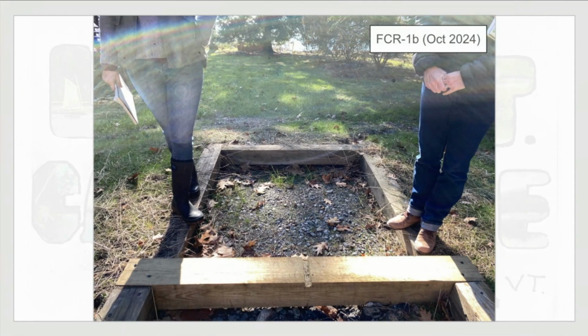And there's another sort of portion of the drainage that comes down the west side of the residence. And these were what we thought were steps that were placed where the runoff is coming down the driveway and exiting onto the grass. And we thought these were maybe intended to be infiltration steps.